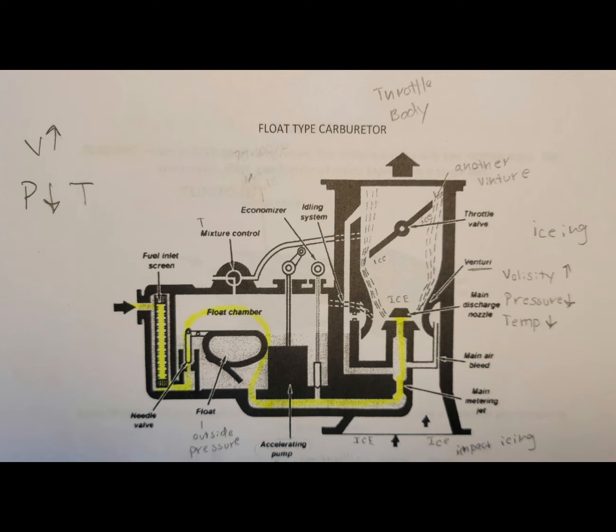What is the function of a metering jet? Limits the fuel flow when the throttle valve is wide open. What will be the result of using excessively rich idle mixtures? Carbon fouling of the spark plug. What is the purpose of the economizer system in a float carburetor? The economizer provides additional fuel at higher throttle settings.